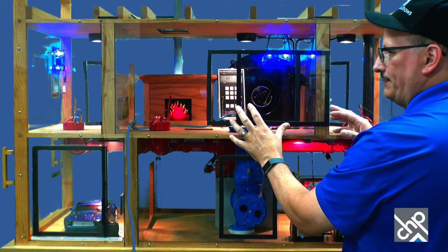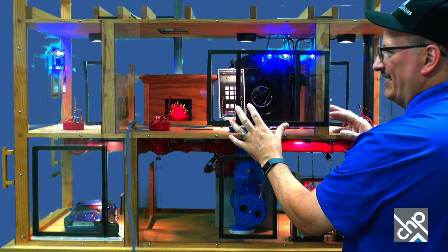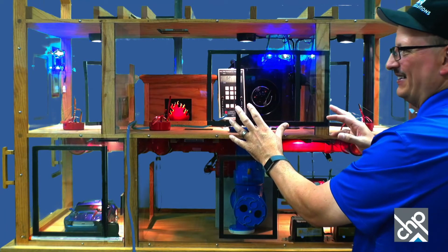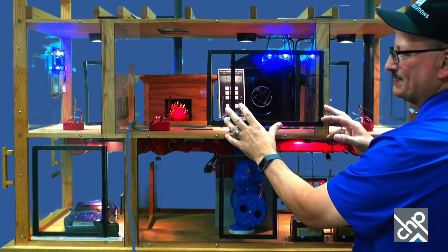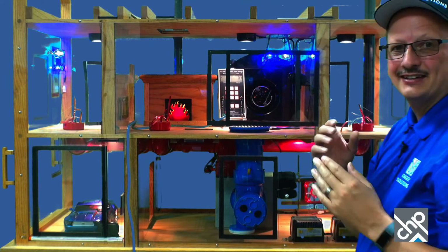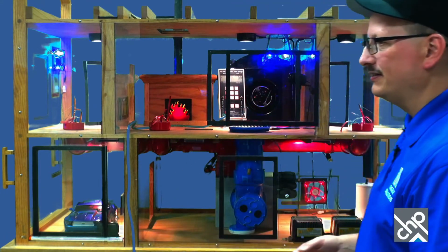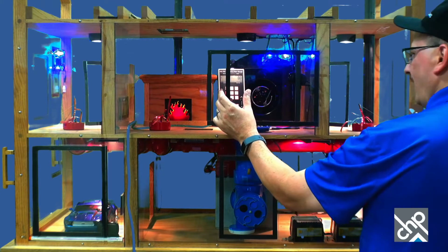As we tighten it up there, you can see it's starting to backdraft. We've got a little bit of theme music here, but you can see the smoke is actually now coming into the house, and that's a bad thing. You don't want the smoke to come into the house. And we didn't even touch the fireplace. It could be a water heater, it could be an atmospheric furnace. But we affect the pressure in the house. So we tighten up the house, we add more exhaust fans, or the exhaust fans we actually have in there. So all those kinds of things.